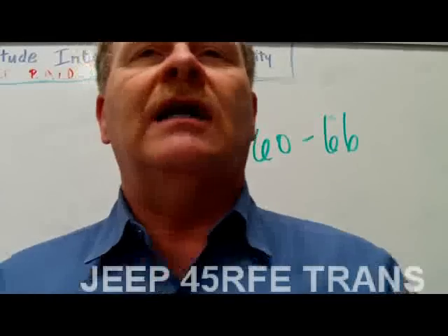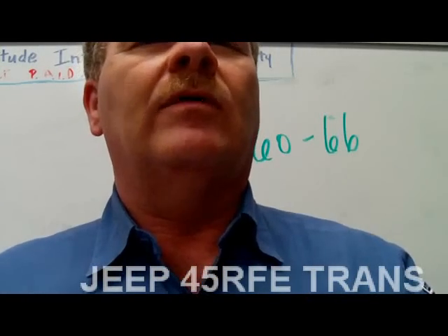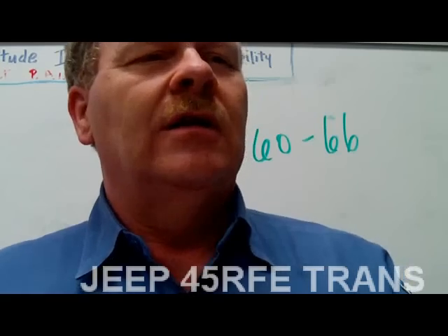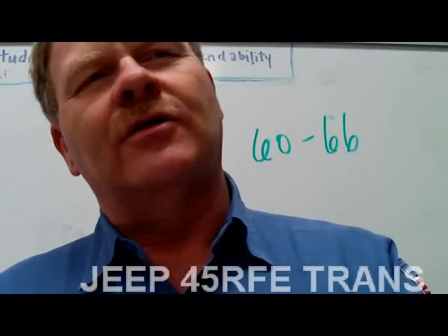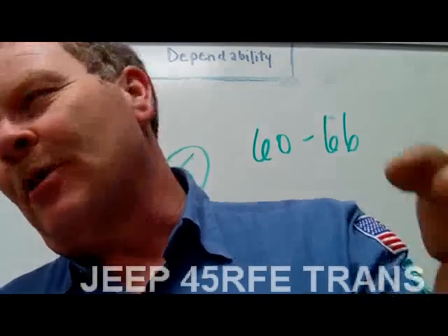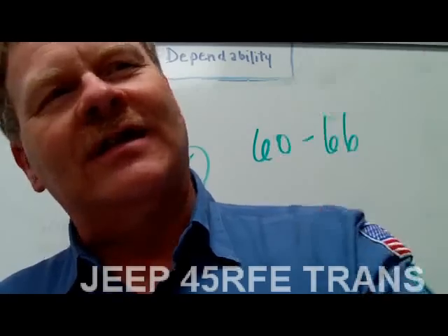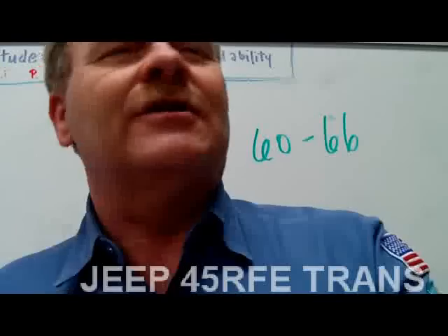Periodically, we piddled around with it, but what the deal was, the transmission cooler in that particular car, if there's enough crud in the radiator, the transmission cooler gets partially submerged in sludge inside the radiator so that it's not able to get rid of its heat. Then the transmission slowly begins to overheat.